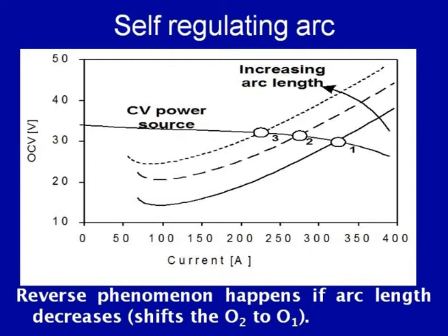So, for the constant feed drive system where a decrease in arc length has taken place, an increase in melting rate will result in the increased arc gap, and so help in maintaining the arc length. That is how the self regulating arc helps to maintain the arc length, especially when the constant voltage type of power source and the constant feed drive system are used. This principle is very frequently used for maintaining the arc length in the gas metal arc welding process and the submerged arc welding process, where small diameter electrodes are used.